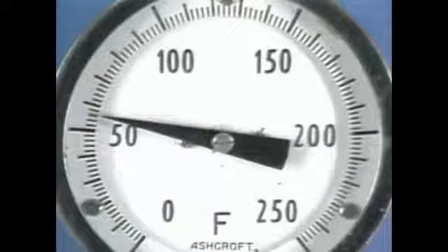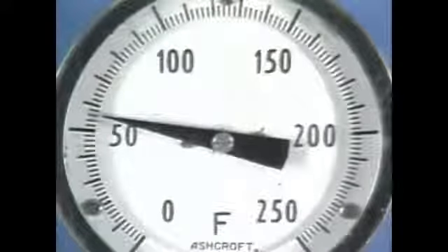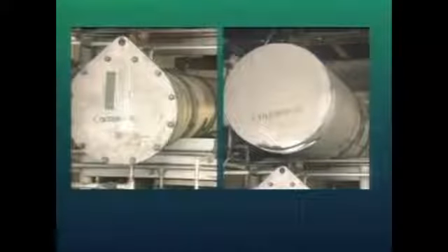A vapor compression refrigeration system may have many indicators to help operators monitor and control the system. These indicators are often located on a panel so that operators can check the operation of the system from a single location. Operators routinely check the temperature indicators associated with a refrigeration system. In most cases, there are temperature indicators for the substance being cooled and for the discharge of the compressor. The condenser and the evaporator may also have temperature indicators located on their inlets and outlets. These indicators can be checked to see if heat transfer is taking place properly.